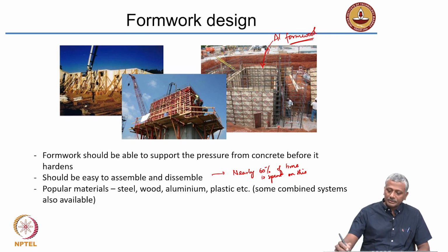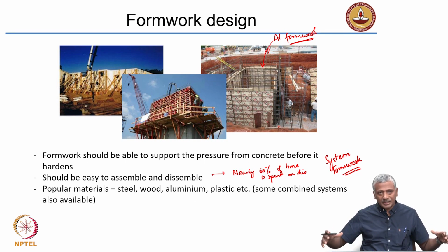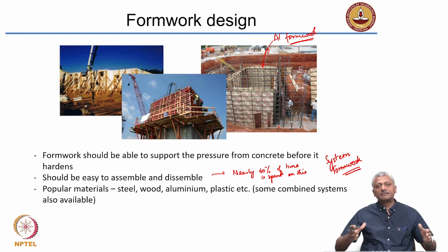So, because of that, today we have what is known as system formwork available. So, for example, you want to build a cooling tower. If you have to design formwork for a cooling tower, it is going to take you a long time. So, you have system formwork that can actually ensure that you are building this cooling tower and this formwork essentially moves up as the tower is constructed. Okay? So, system formwork is an innovation that is speeding up construction practices, okay?